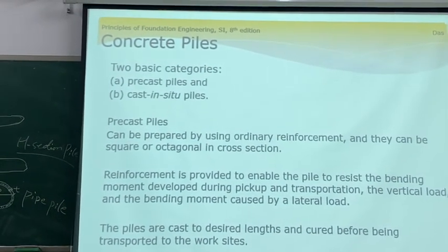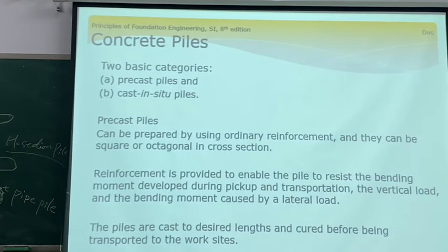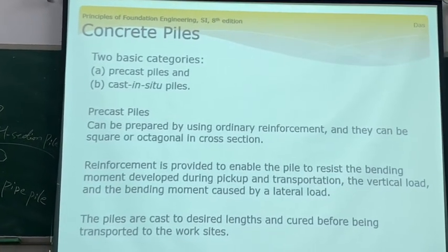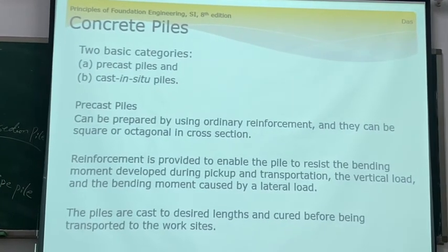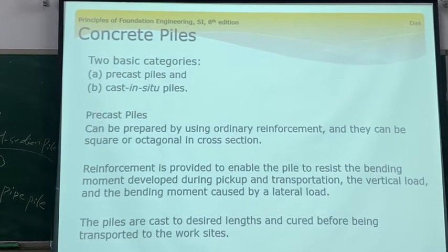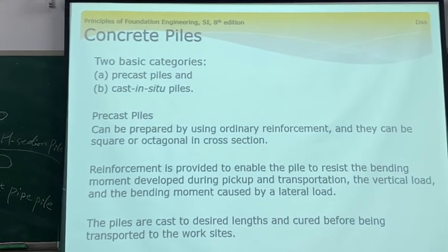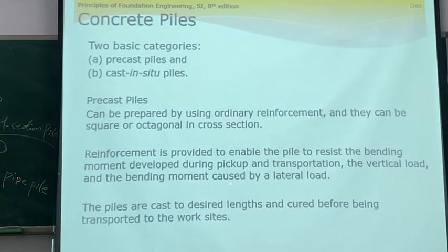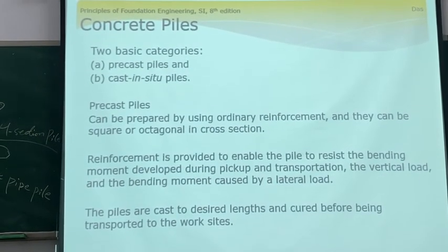When the pile is on the ground, we can use a machine to pick the pile up. Then we move the pile. When you move the pile, the pile may roll. So the vertical load and the bending moment are caused by our own load.